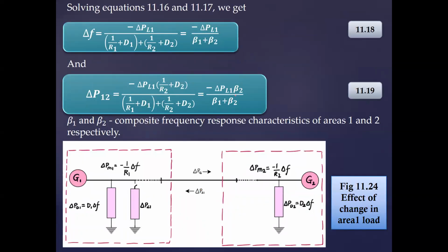So this equation, if I may ask, will give you the optimal power flow to reduce the delta F? One thing again, as I said, optimal power flow we do based on economic generation. But this change in the scheduled power flow, we don't do it in an economical way, basically, because load is dynamic.